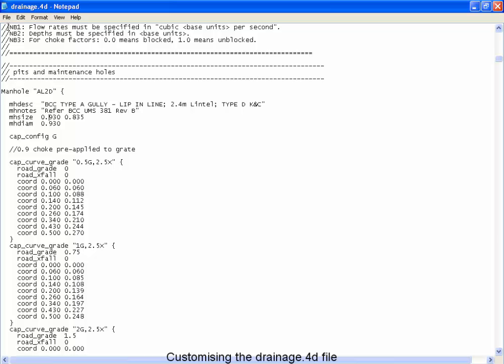Inside our pit schedules, we also quote a length and a width of the inlet. That's where your length and width come from, the manhole size command. The manhole diameter that's used inside 12D is either going to be the default or, if you define it, the manhole diameter size here. So as soon as you select this manhole type, the diameter is changed to 0.93.